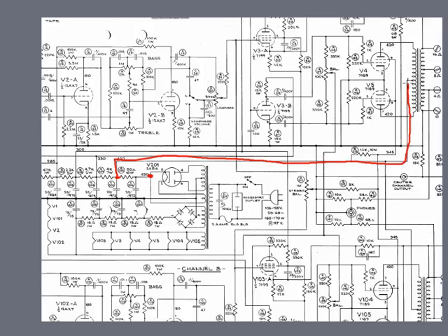Oh, guess what? It's going to the center tap of the transformer, and you'll learn about that later. But then you end up with what? What does it say right here? 420 volts on the plates of both of these tubes in the output. So that's what they needed for the output tubes. Well, let's take another one here. Maybe this 300 volts sitting right here. It feeds across here, comes down to a point right here, and goes across this resistor, probably gets dropped a little more, and that's the voltage they needed for this tube.